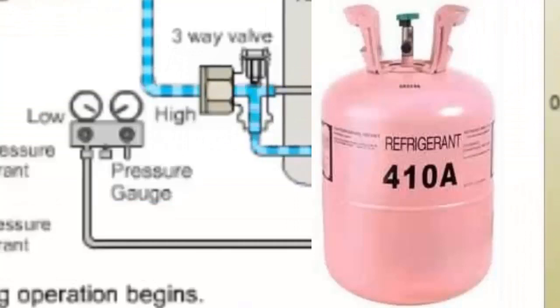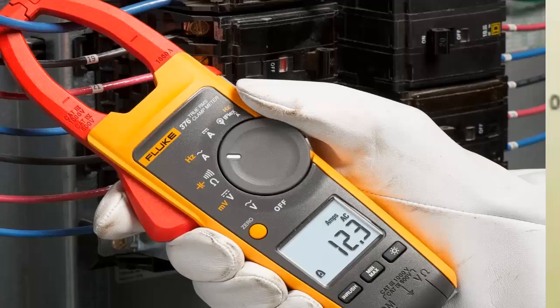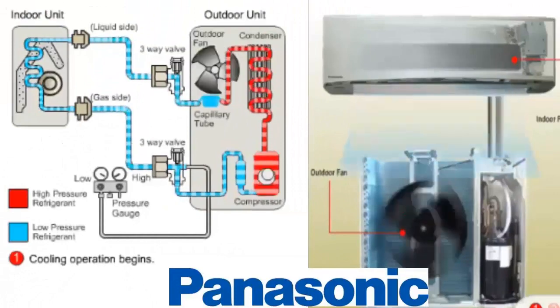The unit cools, but with low performance. In this case, it is necessary to check A. Low refrigerant gas charge.